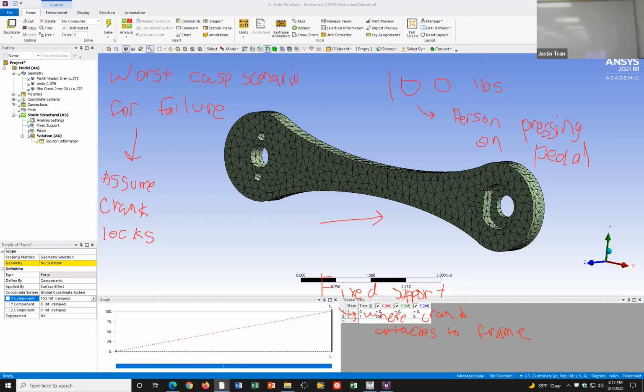After the midterm, we're going to be working mostly with the heat equation. For the heat equation, when we apply a derivative boundary condition, it's going to be a specified temperature. So we're going to say the temperature at this boundary is 50. We apply the same methodology as traditionally, but instead of putting 0 on the right hand side, we put 50. So those are the two nuances.